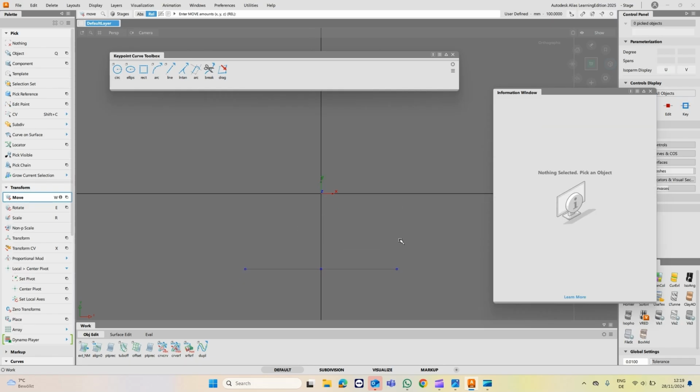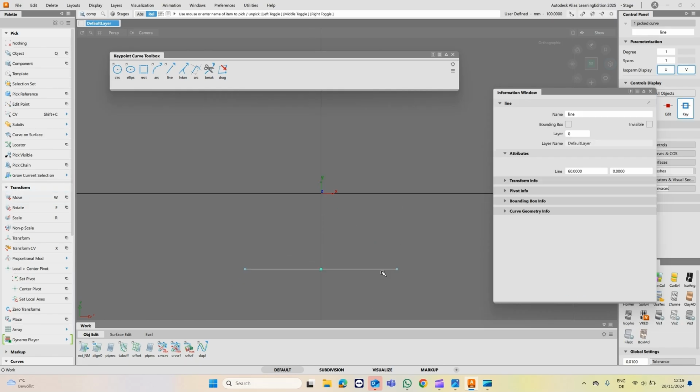Okay, now I'll take that curve, copy paste it, I'll set the pivot, and with control I'll click here next to this point. Control is snapping to CVs, alt is to the grid, and control alt is to curves. Now I want to have this side of it because we've got that, and I want this side here.